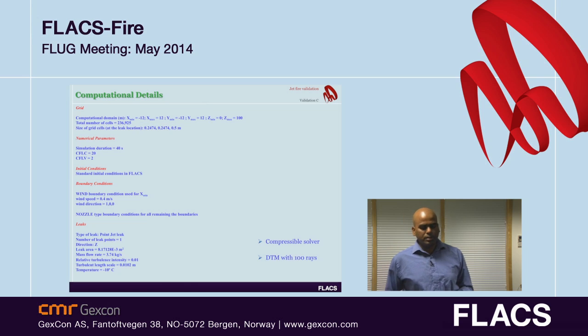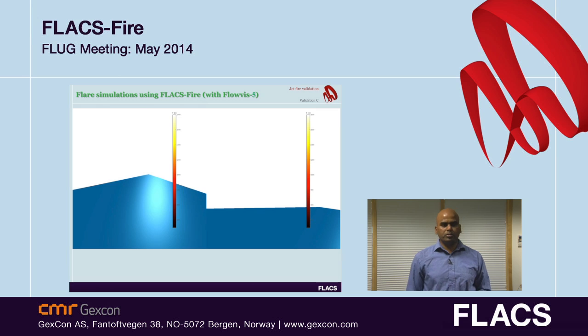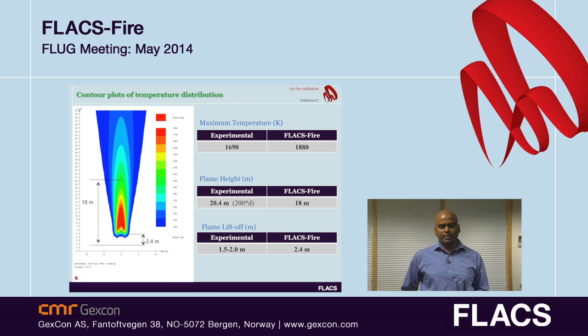This video shows the FLACS-Fire simulation of the flare case which is presented here. Here the maximum temperature predicted by FLACS-Fire is 1880, whereas the experimental measurement is 1690.